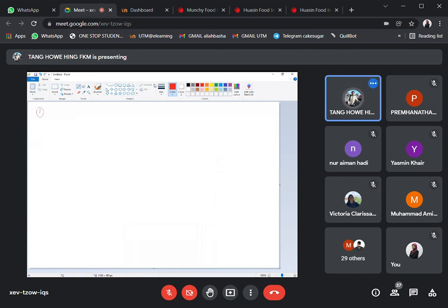The first step is that we are trying to get some form of measurements. All right, so that means we want to know, first of all, for example, let's say this is your load cell, and you have already done all the signal conditioning. All right, so signal conditioning is already done, and then eventually it goes to, let's say, a multimeter. The multimeter will show what the value is. Okay, so let's say it's a voltage.